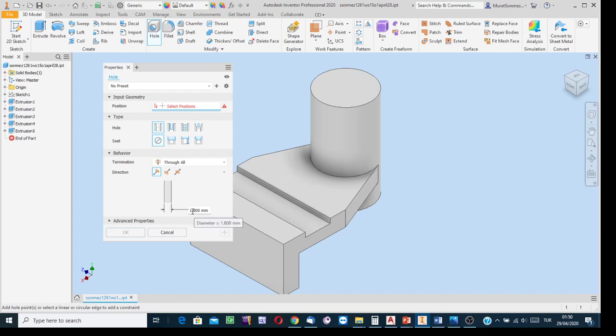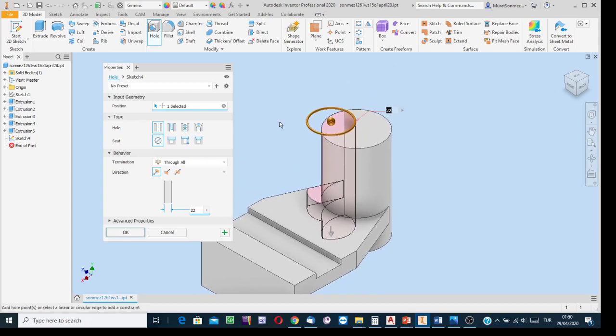And then into this box, write the diameter. Diameter of the hole is 22. The rest: bring the surface onto the starting surface. The hole starts from where? It starts from this surface, and indicate that surface. And then from the pictorial figure, I see the hole is a coaxial hole. Relative to where? Relative to the axis of the cylinder. So cylinder and hole are coaxial entities.